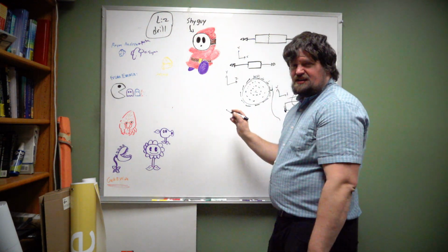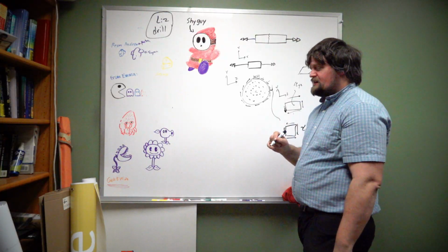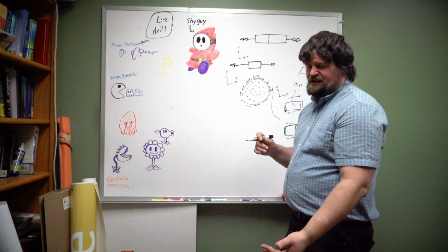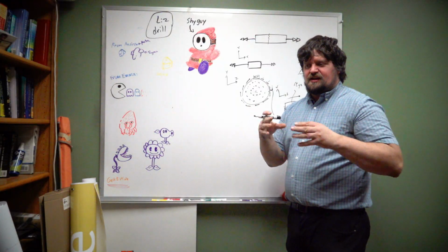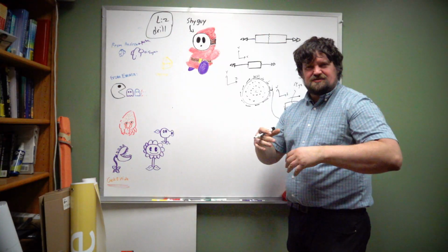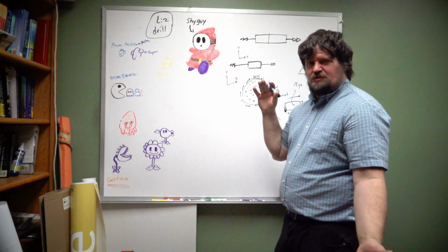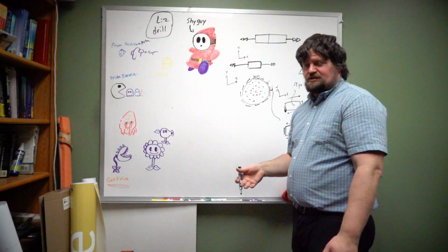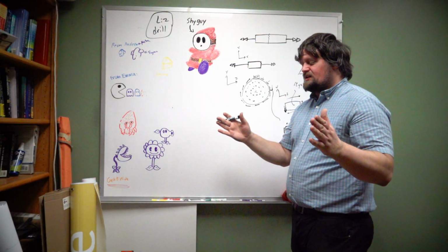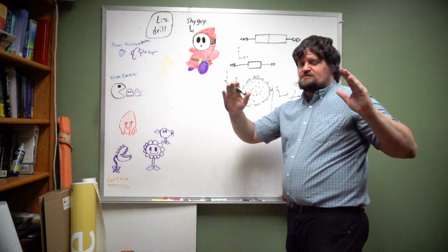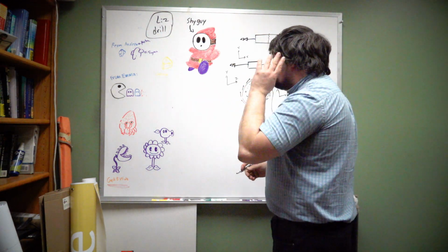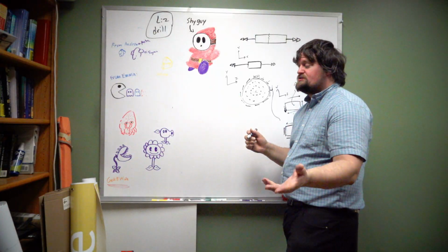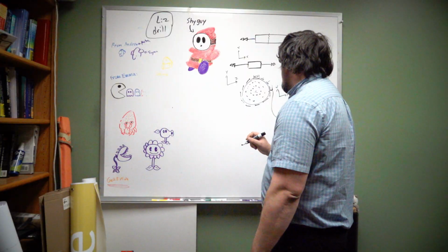Now what we don't see in any of these is any x-directional stresses. I had a student bring up in class that there should be some x-directional stress, and there is, because as you twist it, it causes a compression in it. It pulls it in on itself, which causes it to elongate a little bit. However, the elongation is pretty small, usually, so we typically ignore it because it only really becomes in play when you have a firm boundary on both sides of the rod, so it's not allowed to elongate, which is also poor design practice. So we don't usually deal with an axial load when it comes to torsion, even though there is some elongation in that direction.